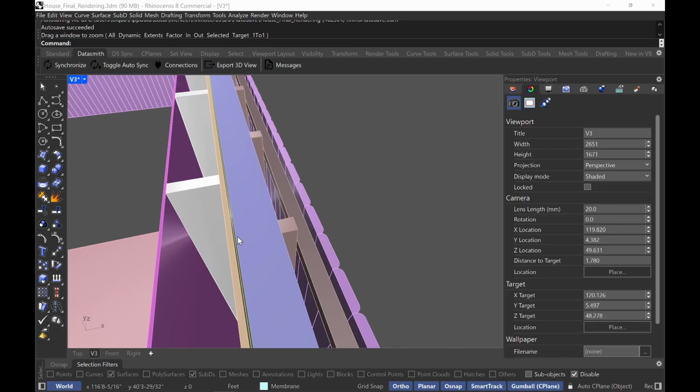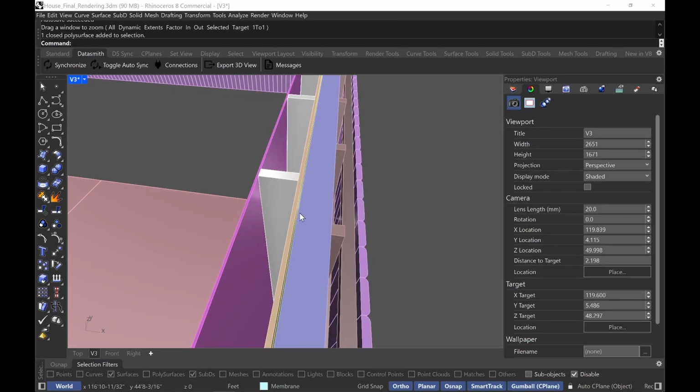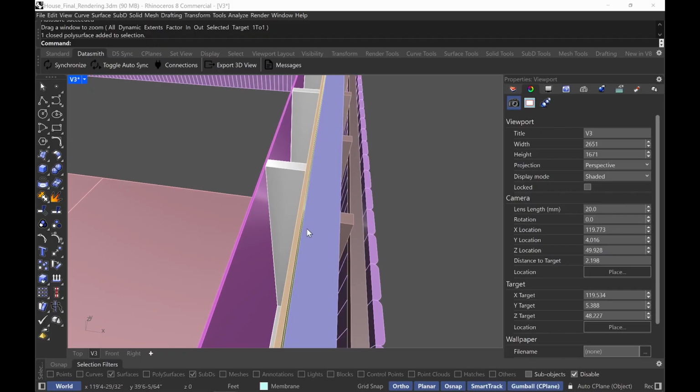The more, I guess, controversial topic, or maybe the topic where you find differing opinions, depending who you talk to, whether you talk to a building scientist versus a builder versus a product representative, is the application of the exterior insulation, right? The location of your weather barrier, and how you identify your drainage plane and like condensation point, okay? So just to break this down.